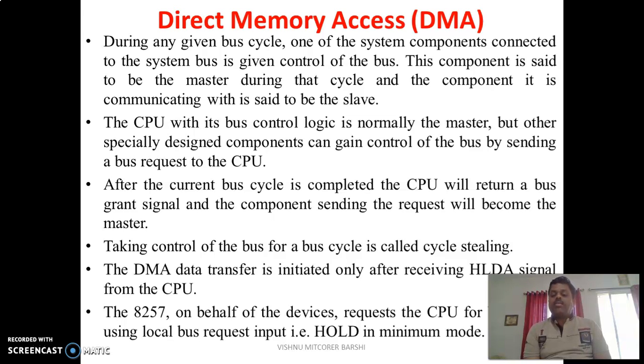Taking control of the bus for a bus cycle is called cycle stealing. The DMA data transfer is initiated only after receiving the HLDA signal from the CPU.